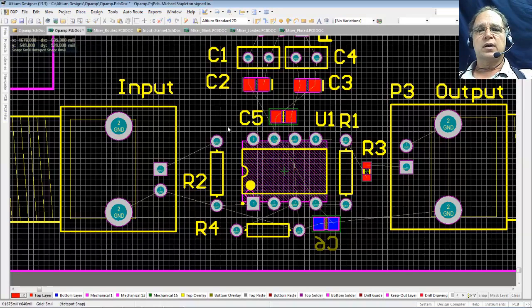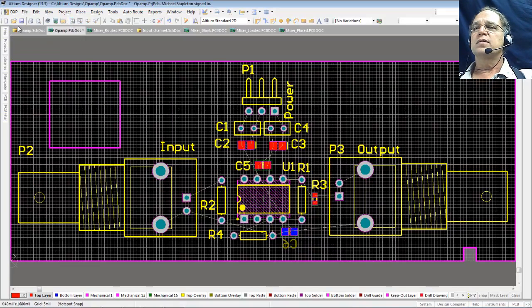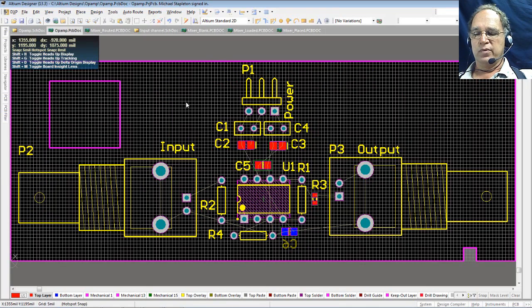So there's a quick introduction to our board shape and our layers, and we're going to see these layers as we keep going. I'm going to add some more layers in our next video, and you'll see about routing, see the copper traces on the top. We'll see about adding planes and adding internal signal layers and removing them, and then we'll also look at changing some of the rules that we have, because Altium has rules, and we'll go and edit the rules, and we can change the width of our traces, the spacing of our traces. So let's do a fit, save all, and we'll finish this video.